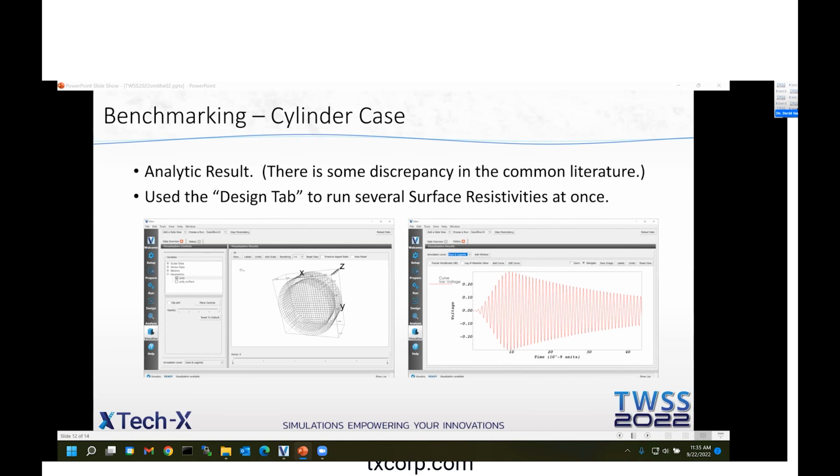Are the dispersion and thickness of skin depth included in this algorithm? No, as I mentioned before, the skin depth is computed from both the conductivity and the frequency. And so that frequency dependence would give you, I think, the dispersion that you're referring to. And so, no, we do not have dispersion. So this is basically single frequency, or what you would call narrow band behavior at the moment.